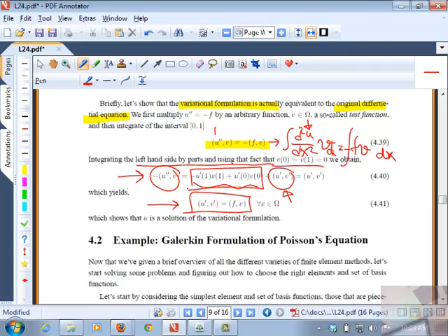In the finite element context, what you will find is, if you know the derivative boundary condition, it's very easy to implement them because the derivatives appear here. So the derivative conditions or the Neumann conditions are called the natural conditions. In your discretization process, you don't even need to worry about this. They are automatically taken care of if they are equal to 0. If they are non-zero, then you need to put the value. But if they are equal to 0, they are automatically taken care of. So that's why you hear that in the finite element context, the Neumann conditions are natural. They fall out of this integration by parts procedure.